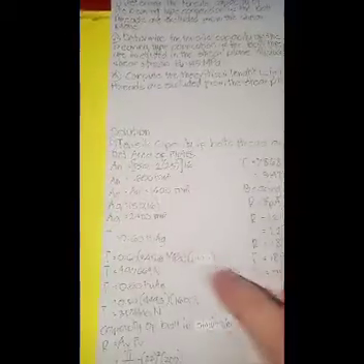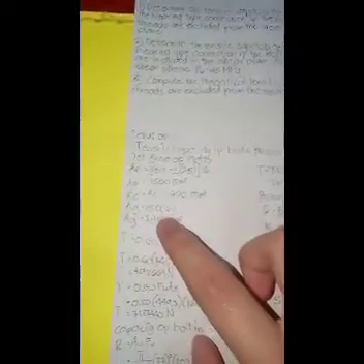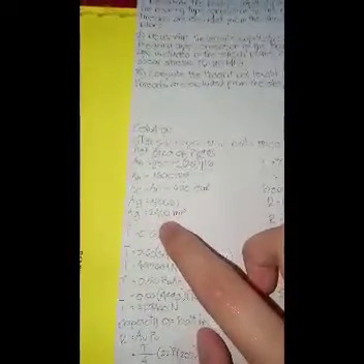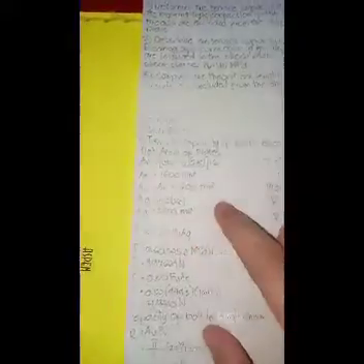A sub g is the gross area of a member at any point, which is determined by summing the products of the thickness and the gross width. So, A sub g is equal to the gross area, 150 times 16. We have an answer of 2,400 mm squared.